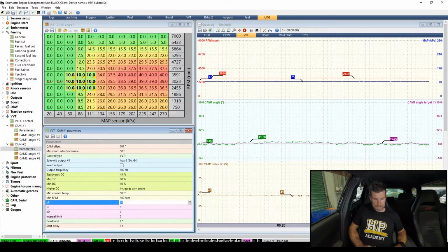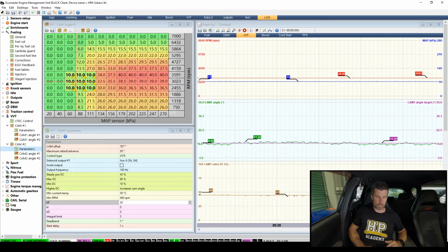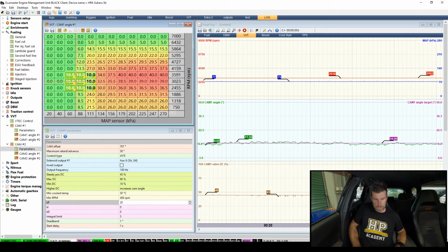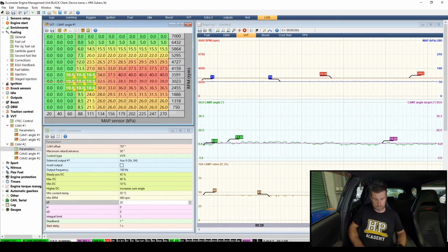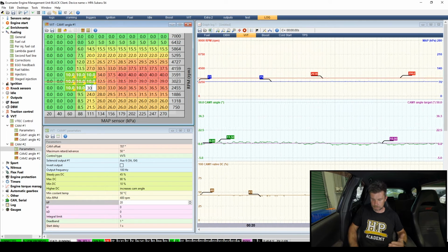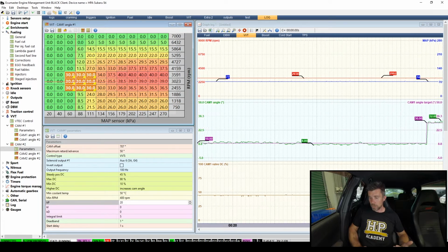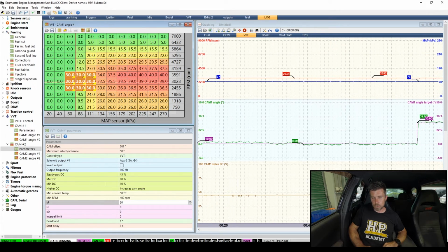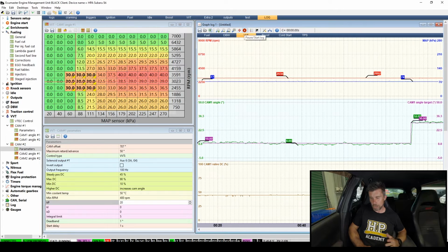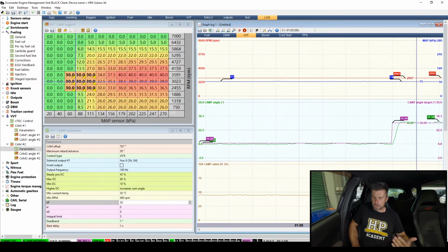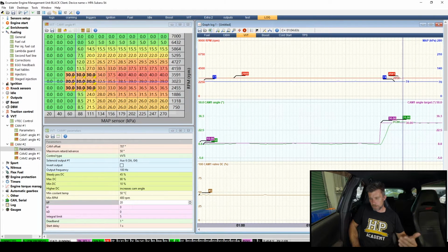So what we'll do now is make our next change. We're going to double our proportional gain element. We're going to go from 10 to 20, and we're going to step from 10 degrees up to 30 degrees again. So we'll press enter and we'll assess our result. It actually looks pretty good, so let's pause that for a moment and have a look at exactly what's happened. Let's start by zooming in so we've got a better idea of what's going on here.